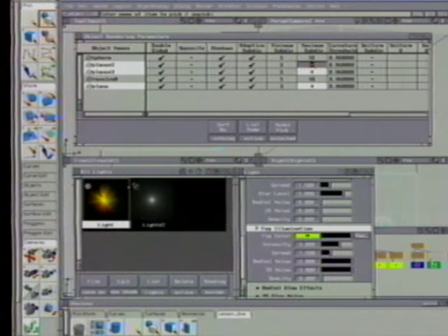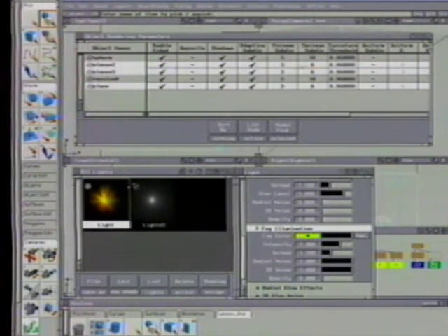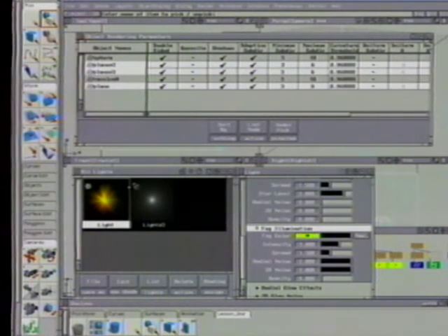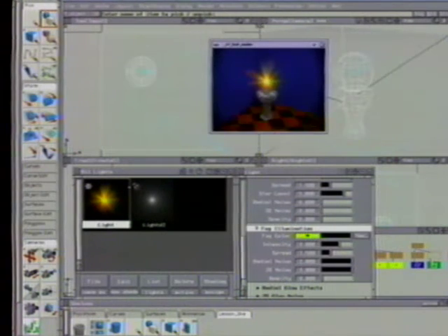Set 3 to 6 for the squares since they do not create curves at all. The more subdivisions the better, although too many will create long renderings with only a little visual benefit to the final image. You must balance the need for more subdivisions to the rendering time of the image.